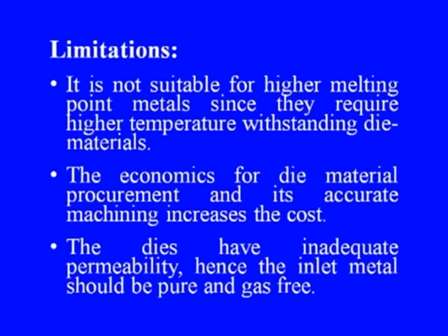Now, let us see the limitations of this process. It is not suitable for higher melting point metals, since they require higher temperature withstanding die materials. The economics for die material procurement and its accurate machining increases the cost. The dies have inadequate permeability, hence the inlet metal should be pure and gas free.